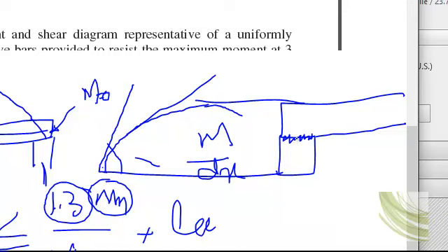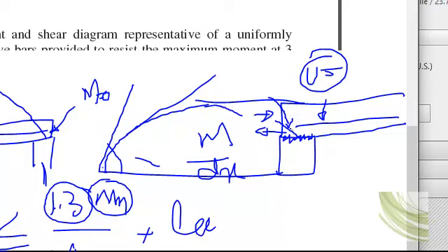Due to bearing stresses, sometimes at this support there is a tendency for cracks to develop. A kind of compressive force occurs there, and that compressive force develops some extra compression in the steel. So due to that compression, the bond forces will get reduced. This effect is larger for larger bar sizes and smaller for smaller bar sizes.